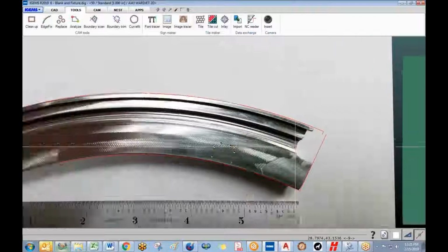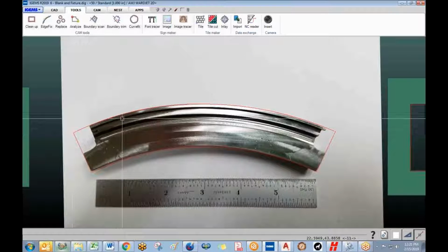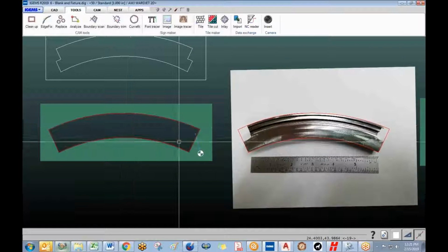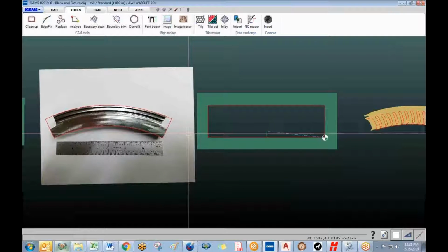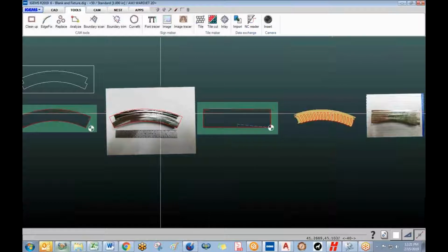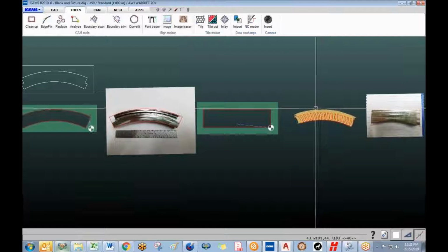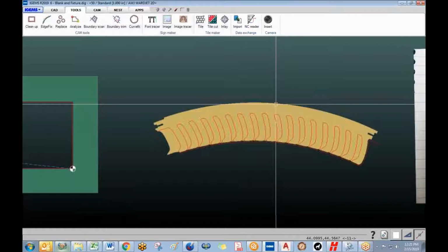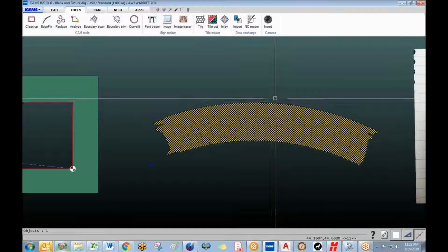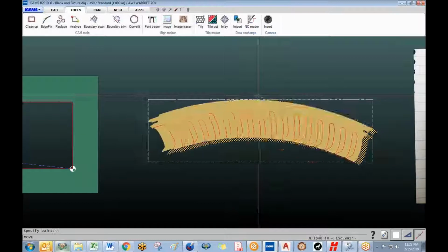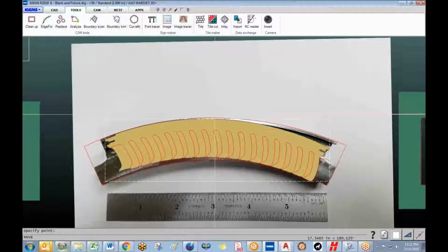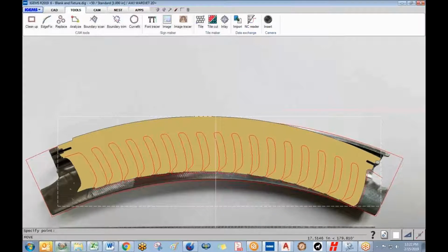Again, I've got my scale in here. Used some CAD commands to draw an arc around here, a couple lines, so that I could create a fixture to put the material into, and then cut the part out of. And then you can also use the same type of tool to make sure that this is actually going to fit onto here. So I worked off of a 3D model that they had given us, which is this image here. What you can do is basically move this, or I'll move it, could copy it, whatever, and bring this on over here. And I'll just turn my snaps off. And then you can kind of place it and verify that it is going to fit on there.